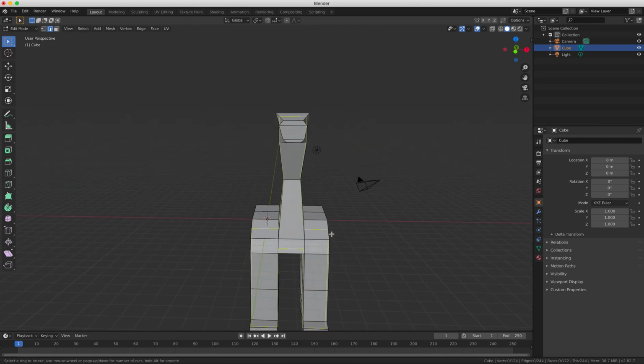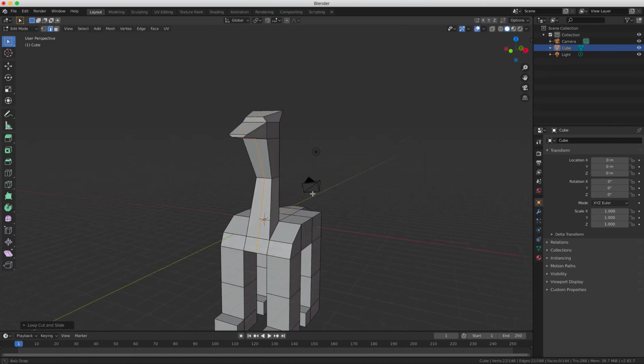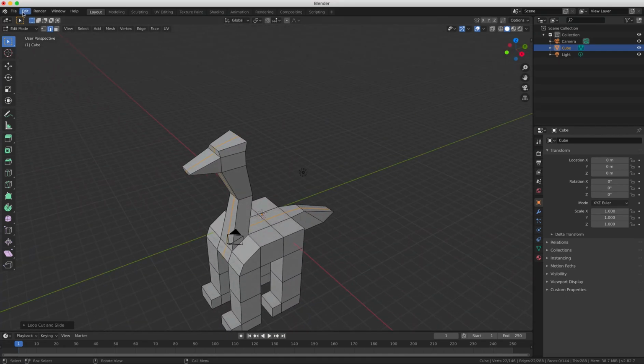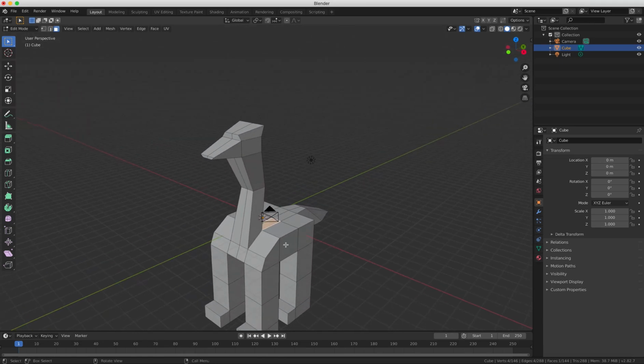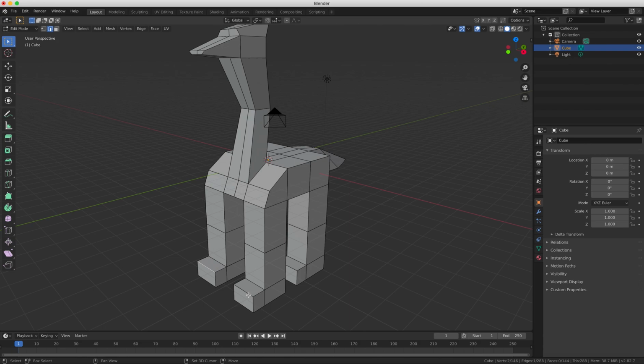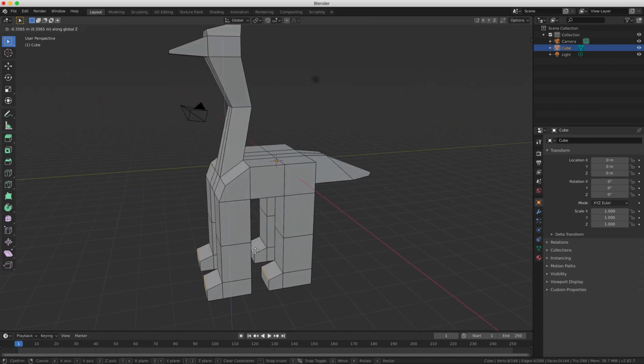Okay, to add a loop cut right down the middle of the body, you can click to center it, or alternatively you can left click and then move the line left or right, and then finally left click again to lock it into place. And we can see what the Loop Cut tool does is add extra polygons or extra faces to our mesh. Finally, we will select the edges and pull them up a bit to add a little bit more detail to our mesh.